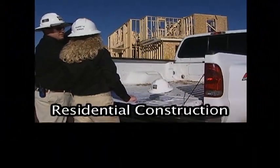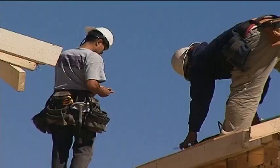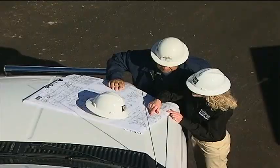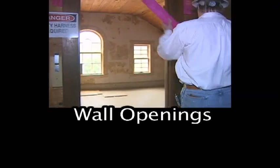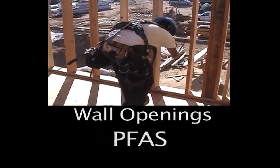Residential construction requires the use of a guardrail, safety net, or PFAS. When it is infeasible to use these methods, or it creates a greater hazard to use these systems, an employer may develop and implement a fall protection plan. Wall openings should be protected by using guardrail, safety net, or PFAS.